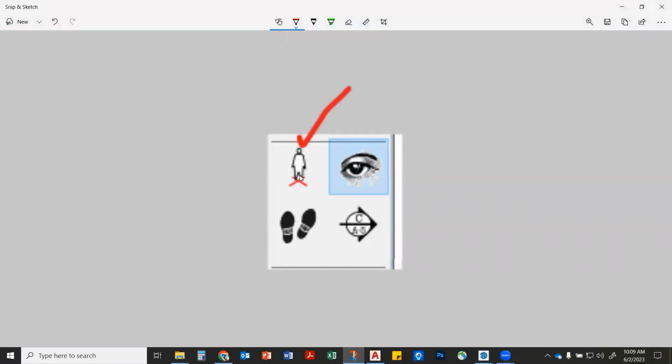So this guy right here sets a camera up, or a view, at the height of a person, okay? So it's really helpful. Why is that helpful? Eye level, right? It's easy to do these big aerial views, which are awesome, but you want to show your client, when you're walking into this space, here's your view. You see this view, right? And it'll actually tell you eye height from wherever you drop it. So it's super helpful, right?